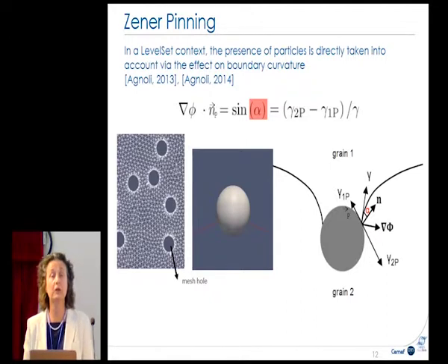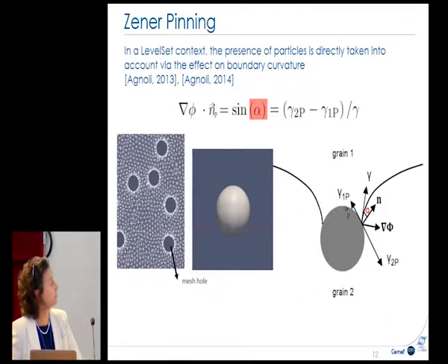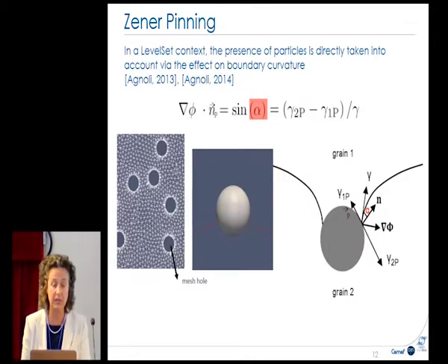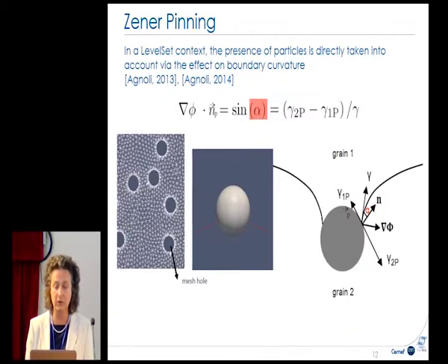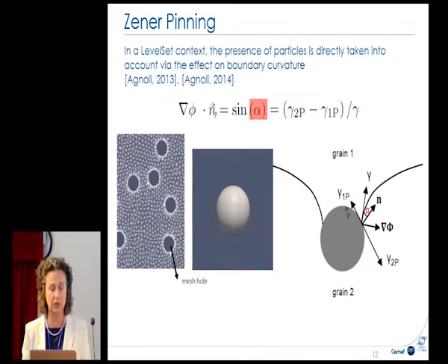So for this grain boundary motion rate equation, we solved it. Here we have the mobility. The mobility is in terms of a classical equation with T the temperature, Q the activation energy, and R the gas constant. This term is the driving force per surface unit.